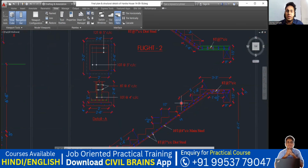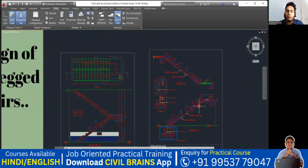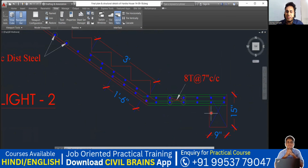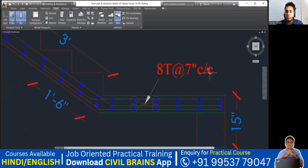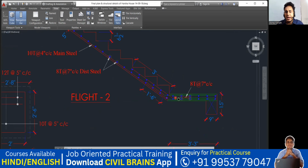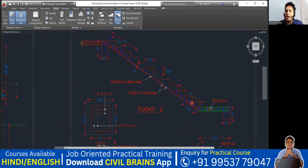Rest, I've explained for one flight. Similarly, this is for the second flight again. Again, this is your landing slab. So in the landing slab, what reinforcement are you supposed to give? Again, it is the same. Your distribution will be 8 diameter at 7 inches center to center spacing. And again, the same thing will go. The bar remains the same only.